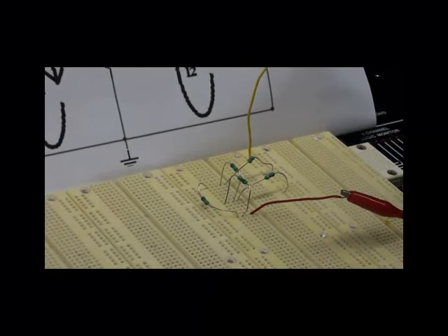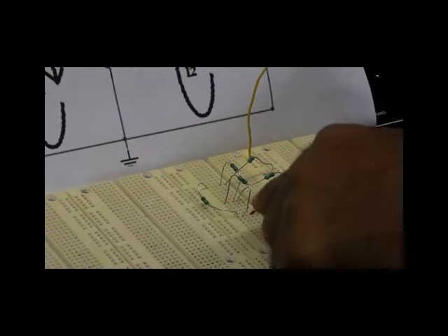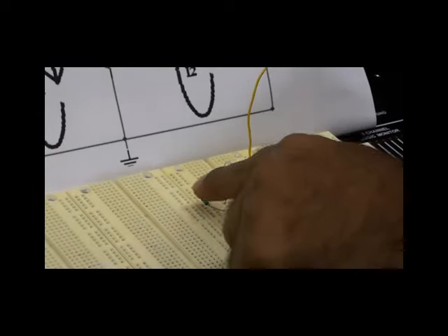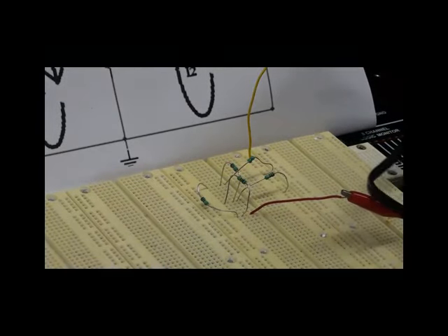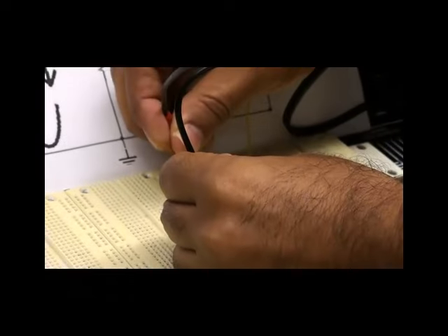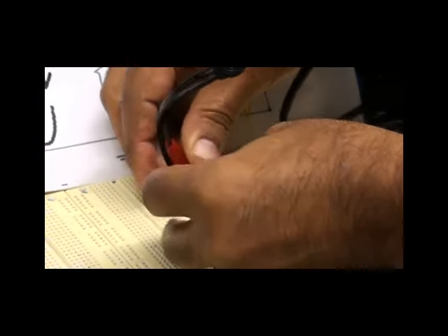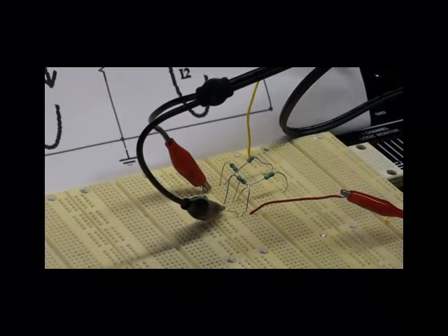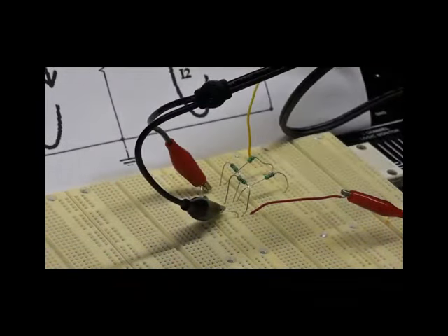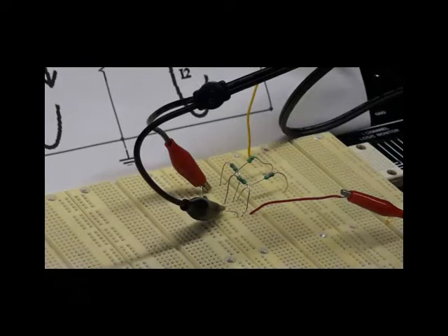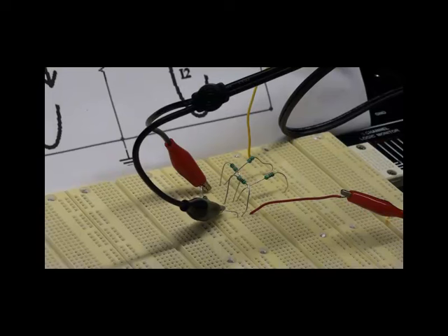If you want to measure voltages, it's really easy. You don't have to disconnect any points from each other. You only connect. For example, in order to measure the voltage across R4, which is this resistor, I simply connect the multimeter in parallel with the resistor. So you can see that simply these two cables are measuring the voltage across the resistor. So to measure the voltage, you simply connect in parallel to the component. No disconnection is needed, as opposed to the current meter or measuring the current.